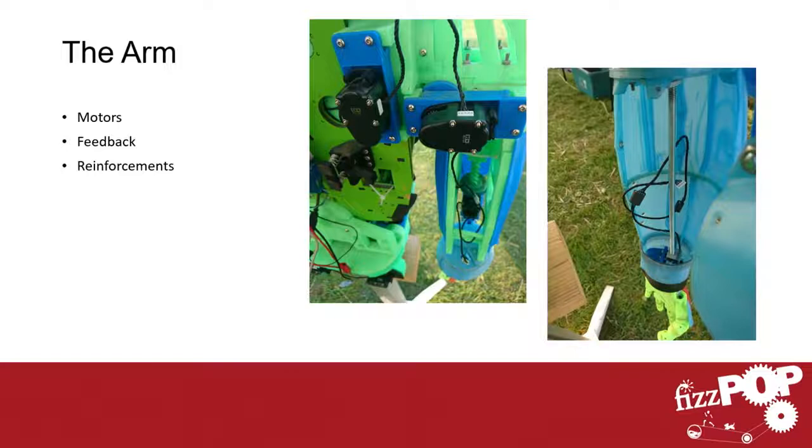And all the motors are addressable, and they can be controlled by a serial connection. So you just send out to each motor ID what motion it should do. So that gives you control of the speed of the movement and the accurate positioning of the motor.